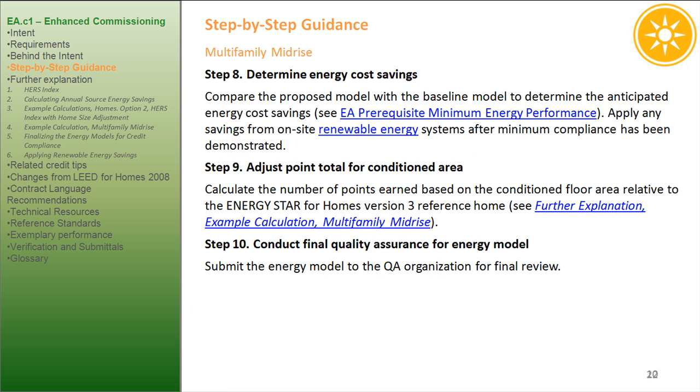Step 8. Determine energy cost savings. Compare the proposed model with the baseline model to determine the anticipated energy cost savings. EA prerequisite minimum energy performance. Apply any savings from on-site renewable energy systems after minimum compliance has been demonstrated.